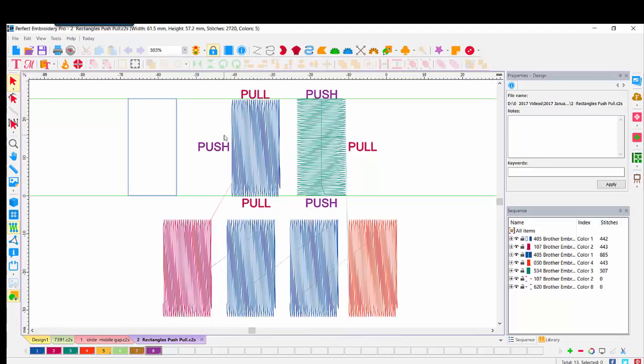If we were to create a rectangle, as we have done here with no changes in default at all, when this stitches out, we are going to expect that the left rectangle will be shorter and fatter when stitched out, and the right rectangle, the green one, will be taller and skinnier when stitched. We base that assumption on the direction of the stitch ends versus the flat ends.